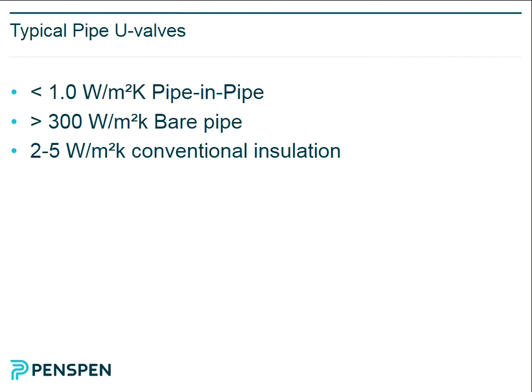It's possible to provide vacuum insulation for tubing, for example. You can buy vacuum tubing, which is a very efficient insulation, like a vacuum flask, for example, where you're separating the inside surface from the outside surface. You don't get convection or conduction, only radiation.